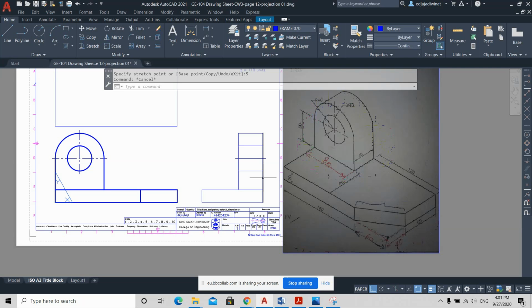From here you offset 60 to the left, or you offset here 40 to the right. I prefer to choose this one because I don't need to trim. But trimming is easy, so without doing this minus that, you can directly offset from here if you want. I will just click offset again, so it is 40 from here to there.